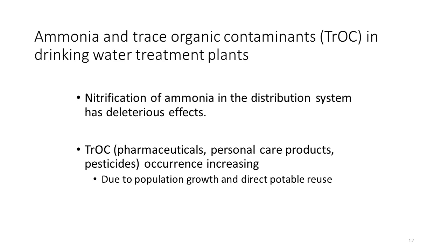Trace organics are becoming increasingly problematic in natural waters, and they are often found with ammonia. They'll probably become more problematic with population growth and as we move towards direct potable reuse. Because we find them together, it could be a really good place to see what kind of impact nitrification could have on removal of trace organics. There have been lots of studies showing that in typical biofilters, trace organics can be removed. So let's see what happens in nitrifying biofilters and how it affects the removal.